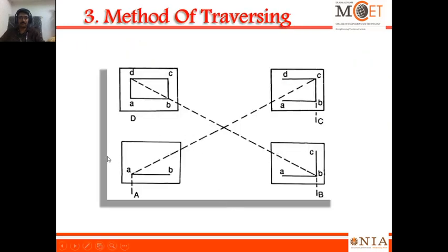Similarly, here the picture shows the first position of the table, where it is centered, leveled and clamped at A. Towards the ranging rod at B, it was sighted and the line was drawn with the measured distance to a proper scale in the sheet. Next, from here itself we can view D also. We can draw the line by sighting D with the measured distance, and the same scale has to be applied here. If not, we can complete it from the other end.